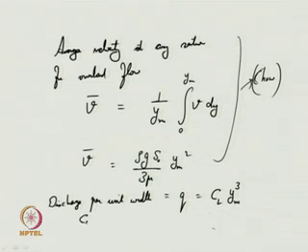So, your CL is nothing but the coefficient, the same coefficient rho g s naught by 3 mu, it may be observed like that also. You may see such phenomenon. Like this way you can compute uniform flow for overland flow cases also. So, today we would like to stop here. As a matter of interest or curiosity, I can just ask you one question.